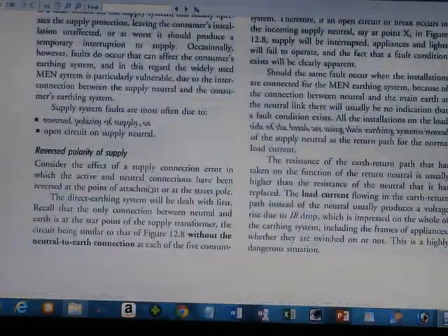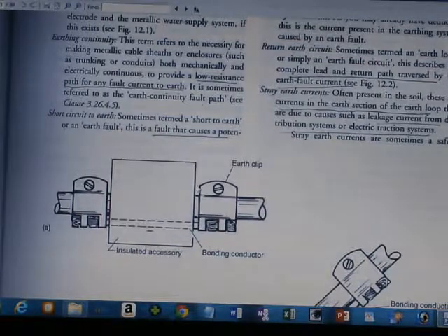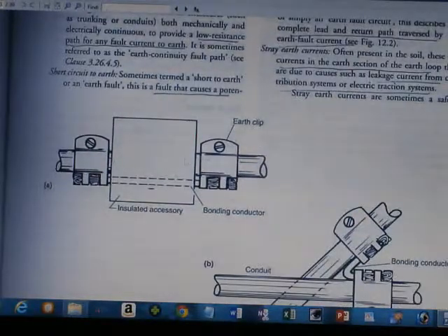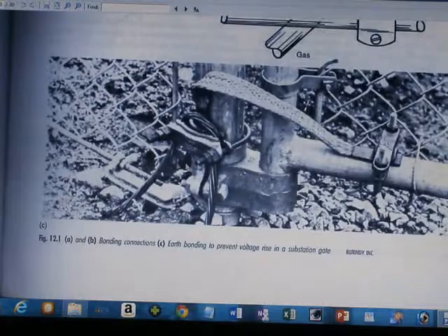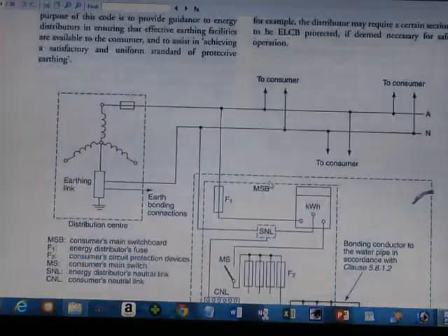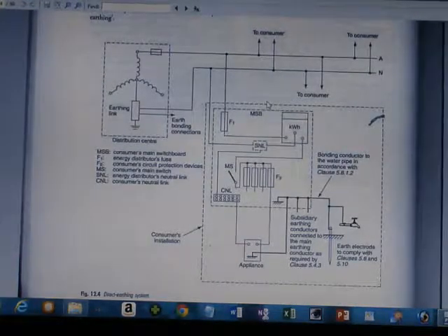So these are all the wires and continuities of the earthing system. This is the connection of the electrode, and those are the typical views of the earthing system. At the earthing system you can see the three-way star point connected to earth, and this way we just earth the ground wire. This is a neutral wire and earth combined, and this is the main switchboard.